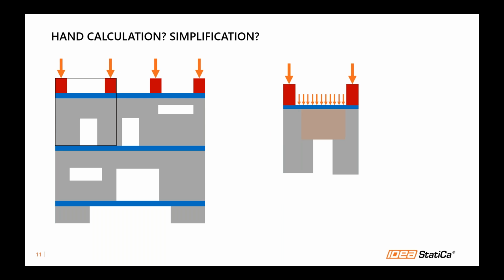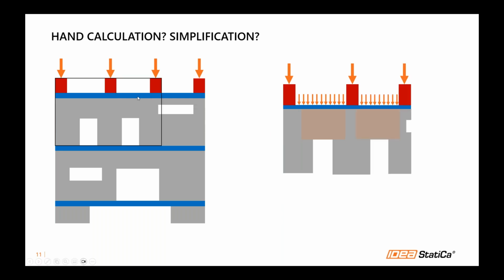So yeah, then okay, because this encroaches here, why wouldn't I just take the whole thing and design both of these deep beams together instead of figuring out how to transfer or how to split the load between the two? But then the question is, you can see on the right side here it actually encroaches into another opening here, right? So the same question again, how do we distribute the load from the third column here?